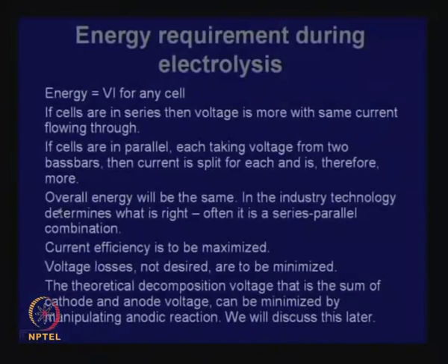time you like. No matter what you do, our aim will be to maximize current efficiency, because we do not want the current to go for anything other than metal deposition, except in the case of high temperature electrolysis, there the current also has to provide heat, because after all you will not heat a pot from outside.